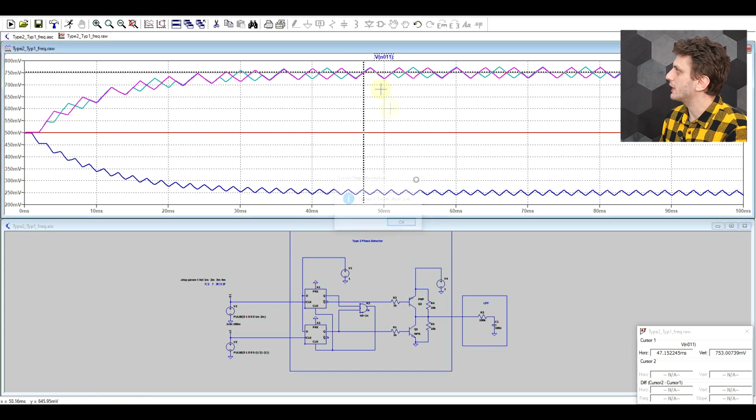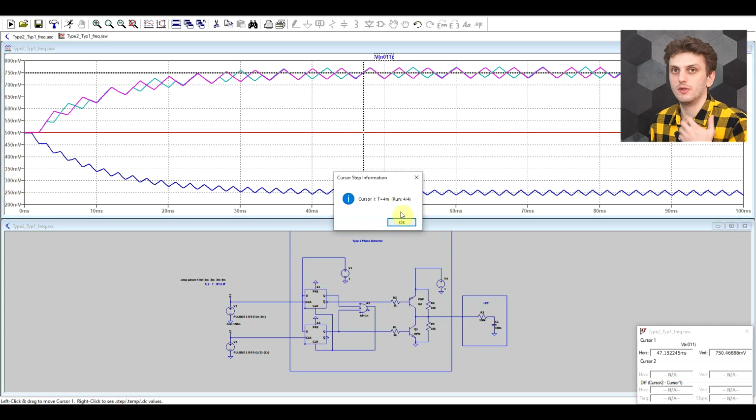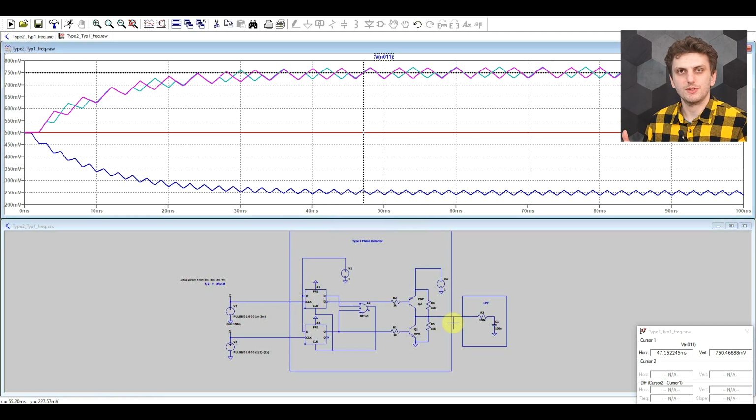And then above we have the two cases in which we had higher frequency. So 3 halves and the double frequency. So the type 2 phase detector is also called a phase frequency detector because it gives a different response if the secondary signal is at the lower frequency or at the higher frequency than the reference signal. So we can see that clearly here that when we had higher frequencies we had higher values, when we had lower frequencies we had lower values.